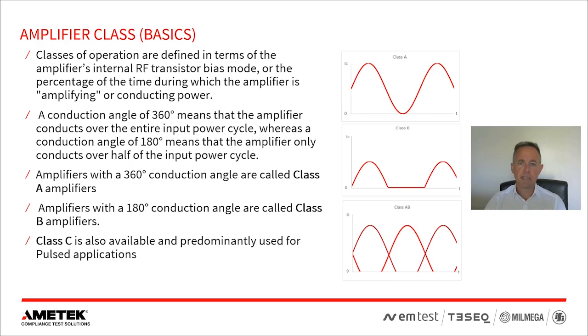A compromise between the two is the class AB amplifier. This is a combination of class A and B, surprisingly. This allows for both halves to conduct at the same time around the waveform's crossover point, eliminating the crossover distortion associated with linearity problems, leading to a reasonable linear performance at a better efficiency. Due to the large amount of non-linearity they create, Class B amplifiers are generally unsuitable for RF applications. So most, if not all, CW RF amplifiers are either biased in Class A or Class AB.